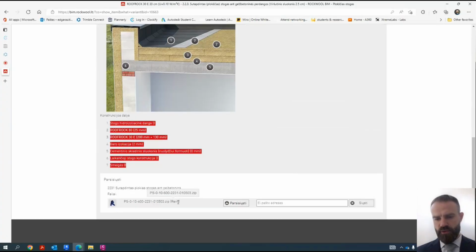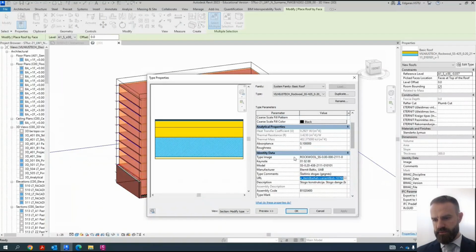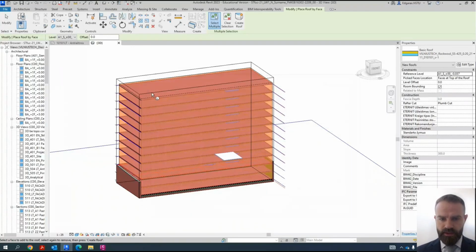So when you open this Revit file, you just copy paste or use transfer project standards option, and you can move data from one file to another. So it's nice option for the project to have nice structure and nicely filled up with all the description and all the comments. Okay, so for the roof, I will use this one, select the roof, create the roof.